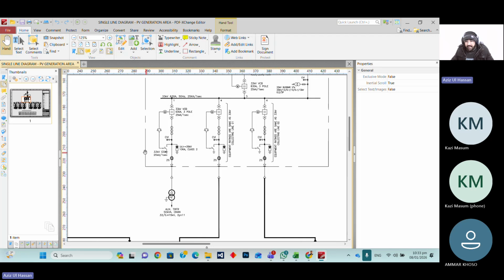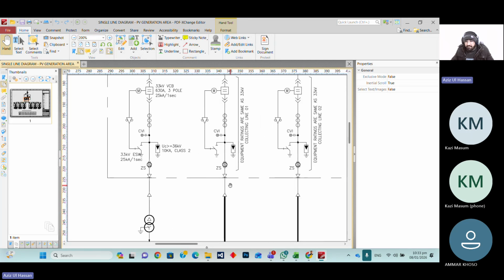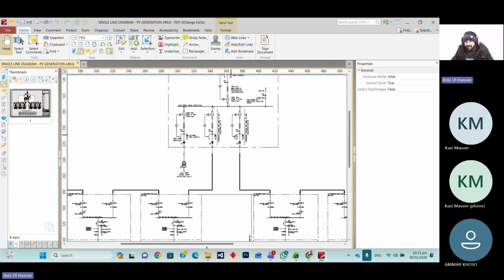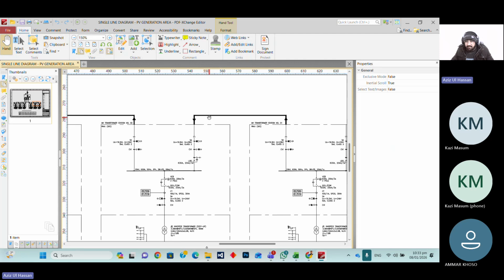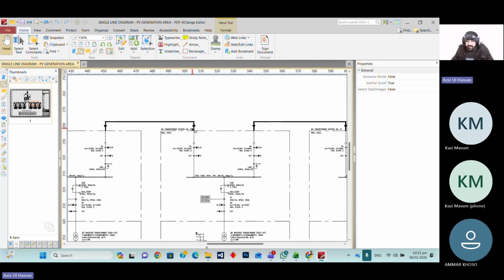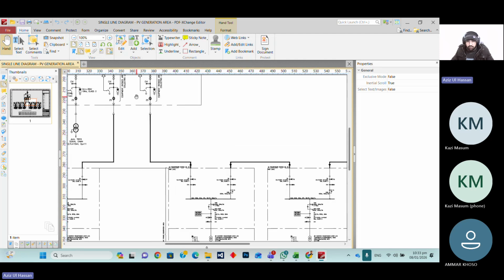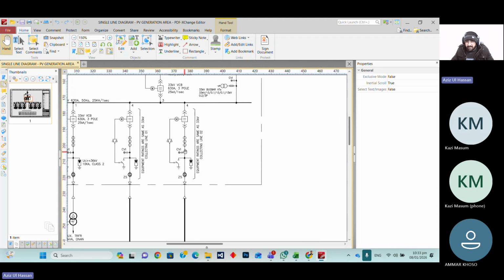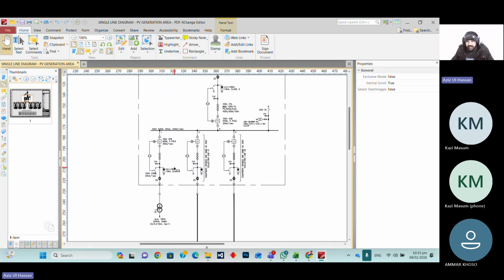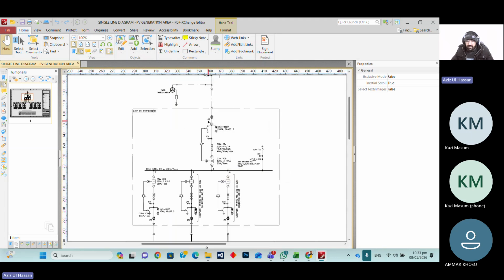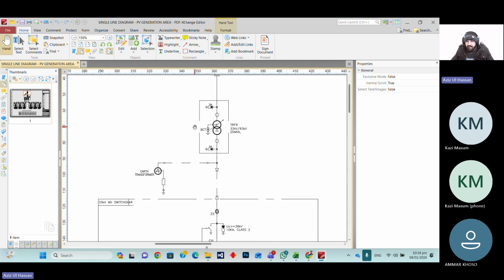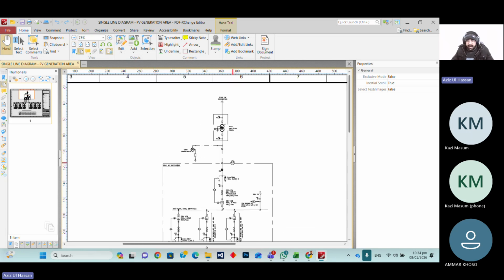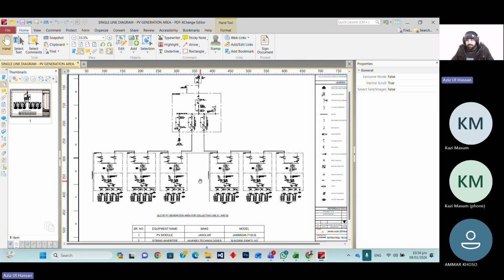This is basically the MV substation switch, MV panels. Here we have terminated that cable feeders. Again here we have another feeder. Like we have this transformer connected to the output, and then their output should be connected to the input of that, and their output should be connected to that MV panel. So here we have two MV panels, and then their output bus bar, and then their output panels, and they connect to the earth transformer, and then the POC connection. So in that way, we will connect in the large scale projects.